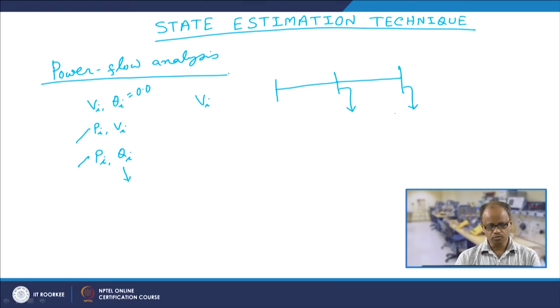If we do not know their exact values, our load flow calculation itself would be erroneous, and we will get erroneous values of voltage magnitudes and angles at all the buses, and also erroneous calculated values of power flow over a line as well as the line current magnitude. Therefore, we need to put meters here.